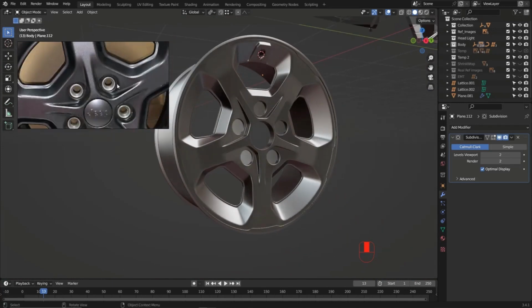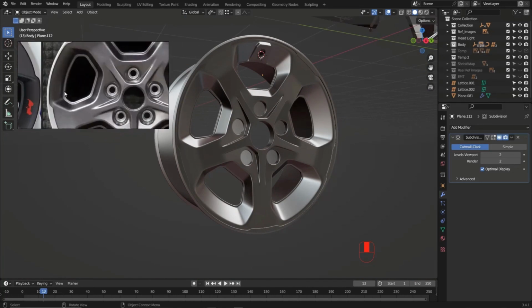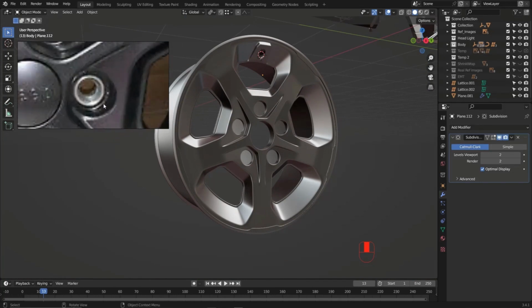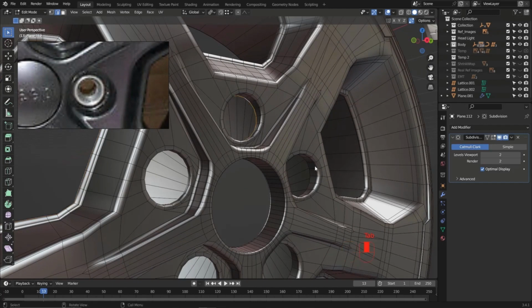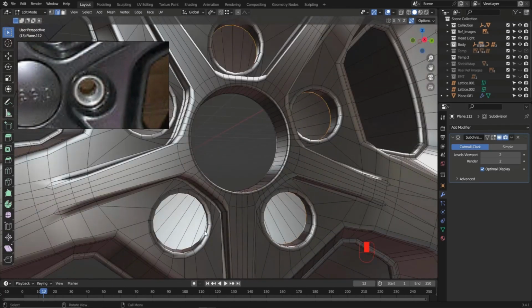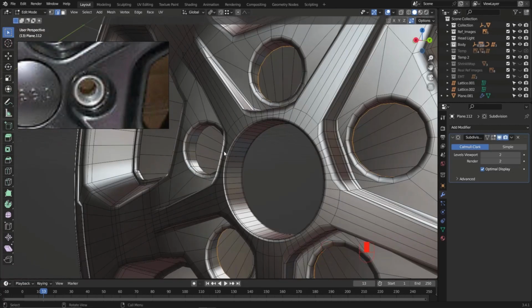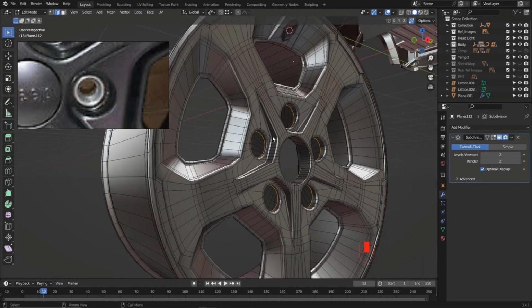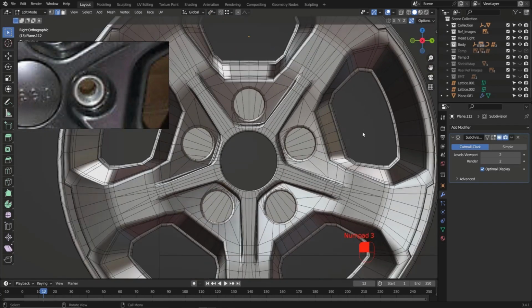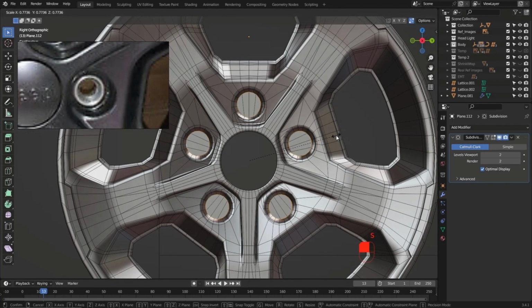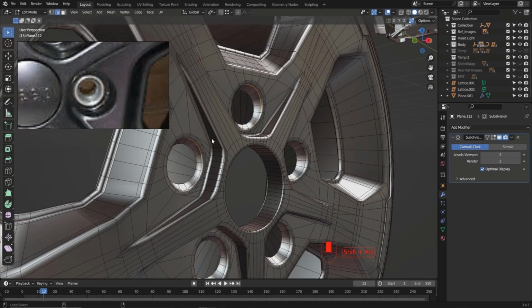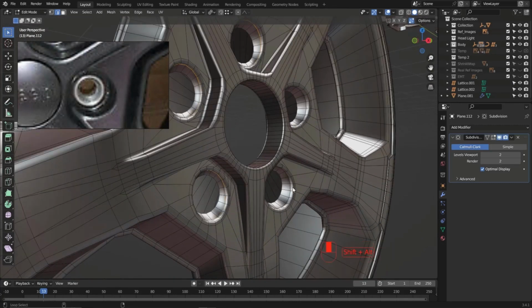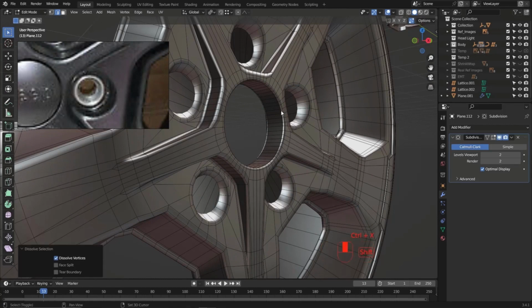I just noticed that when I moved from this image to this image, I think here we have a taper shape. If you tab to go to the edit mode, let's grab these circles and those over here, and let's change this to the individual origins. Go to the right, hit number 3, and let's scale those inside like that. And now let's delete these edges that we added. Hit Ctrl X to dissolve them.